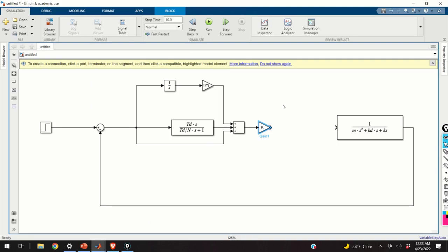Actuators cannot exert an infinite amount of force, cannot exert infinite torque, cannot exert current that's infinite in value. Consequently, in order to simulate realistic actuators, we need to put some constraints over here, right? And these are the so-called saturation constraints. Of course, there are other types of nonlinear constraints such as dead zones, hysteresis, and other types of limits. However, we are not going to discuss them in this video.